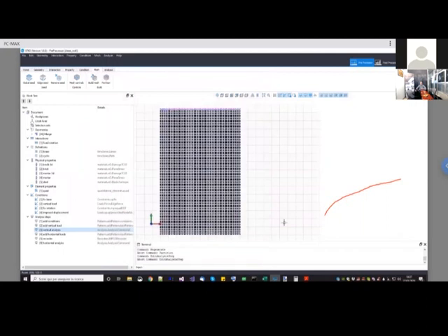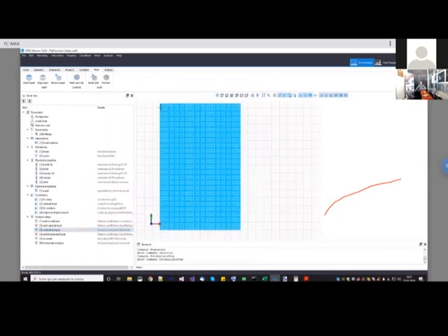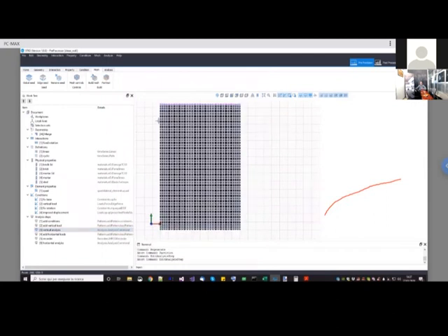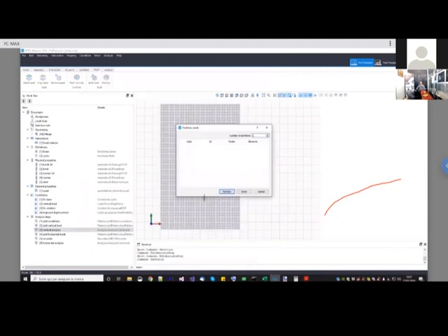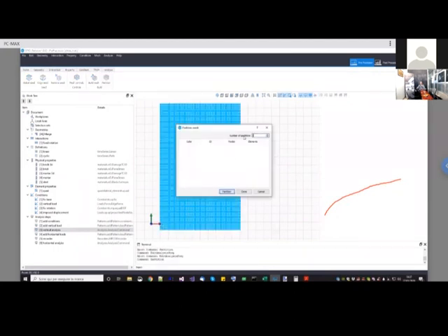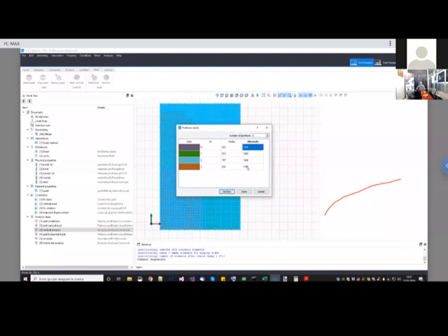Of course, don't think that if you have many processors, your analysis will always be faster. It depends. You need a very large model. For example, I've seen that if I want good speed ups, I need at least something like 1,000 or 2,000 elements on each processor. So, for example, here I have 6,000 elements. I can get improvements if I take, let's say, 4 partitions, but not more, because with 4 partitions, I already have less than 2,000 elements per processor.